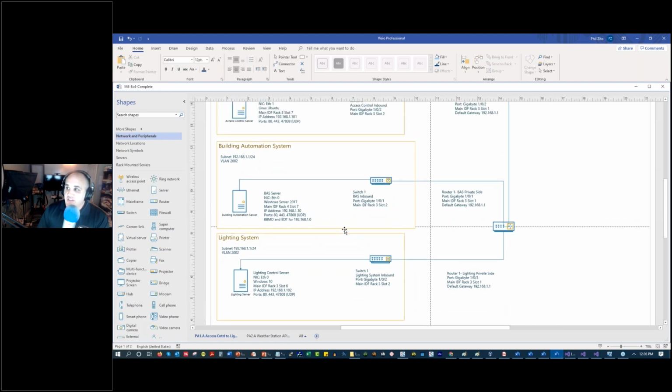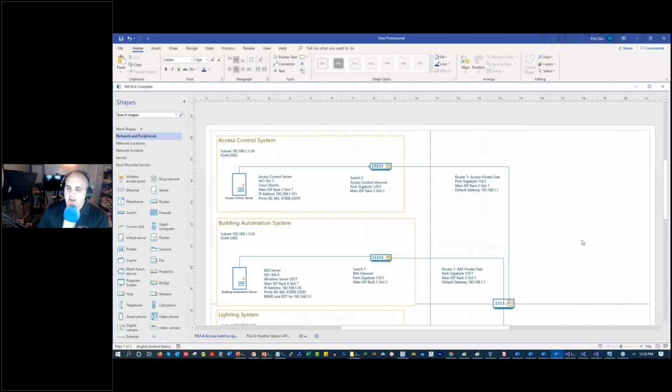As I mentioned, physical setup is a really big mistake area that people make and don't properly integrate. Then they're wondering, why is my integration not working? Well, you're on a different subnet, right? I can't count how many times I've gone out to troubleshoot the simplest BACnet integrations, and they're on different subnets, or one's 47808 and the other's 47807.